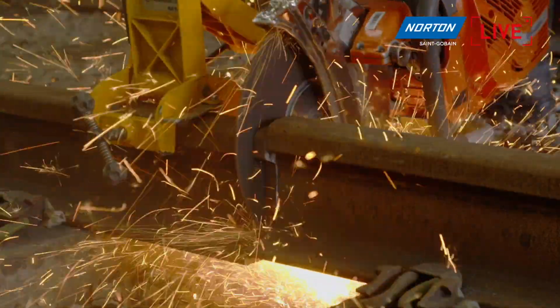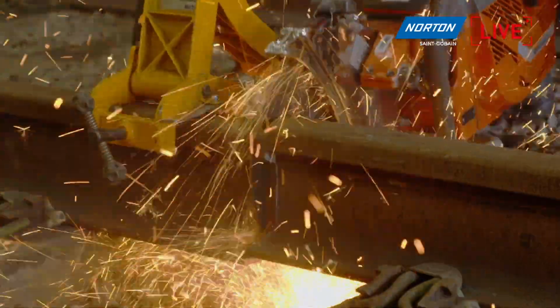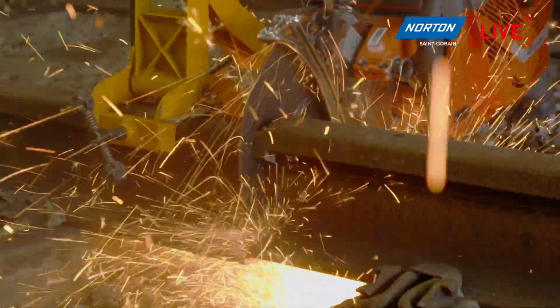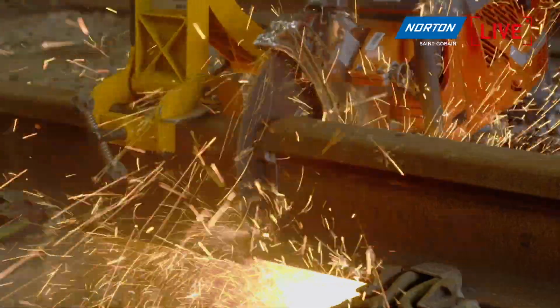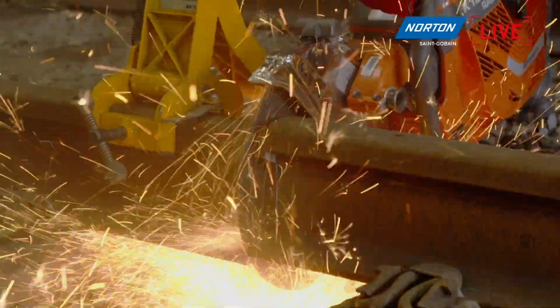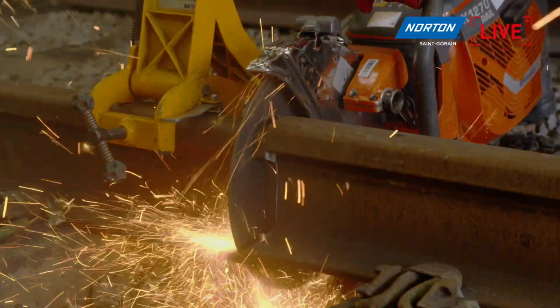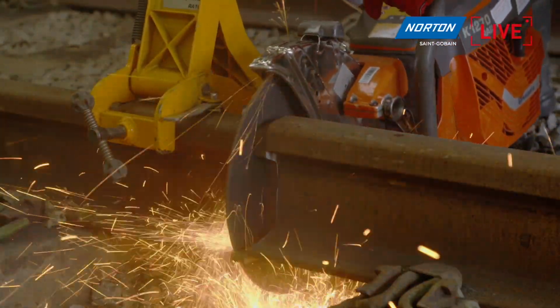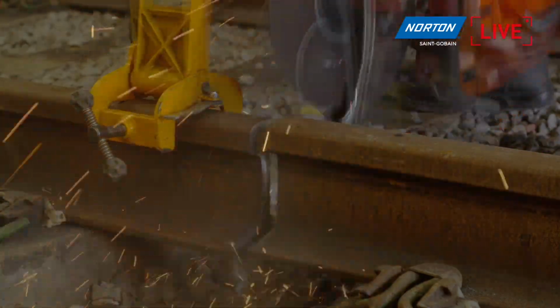All in all, this cut takes about 1 minute with a Quantum 3 blade that we're showing you today, which is a really fast speed of cut. Again, look at the sparks. I think the point to note is that this is UIC 60, the larger rail section you're seeing here. So this is why we have a 350mm diameter blade through this, so you can get a couple of cuts from the blade without swapping the machine over to the other side, which is crucial, isn't it?